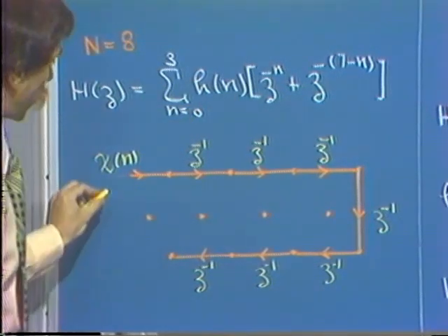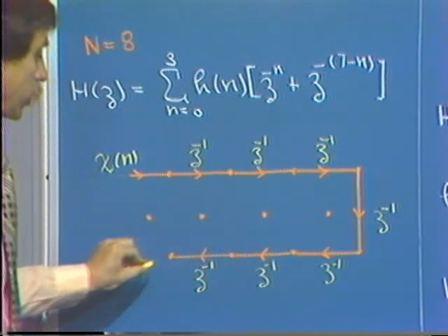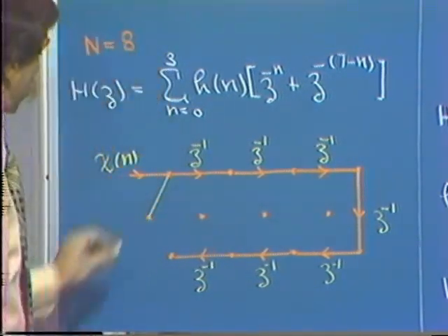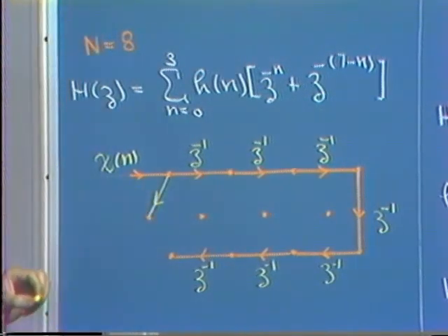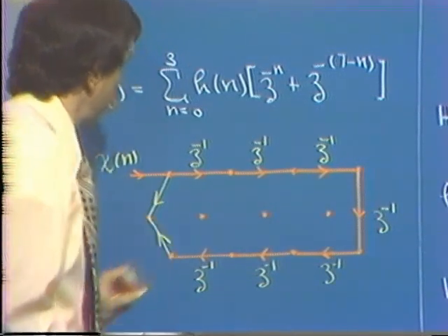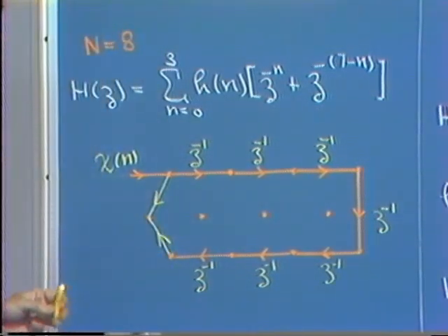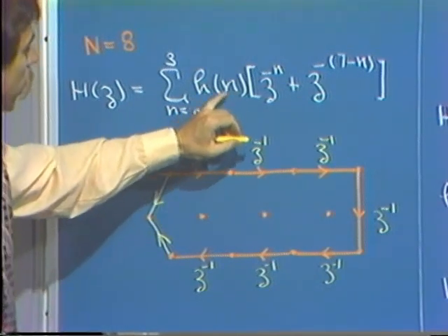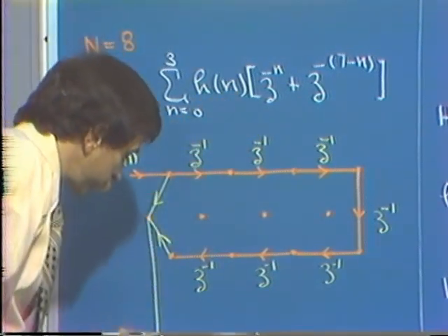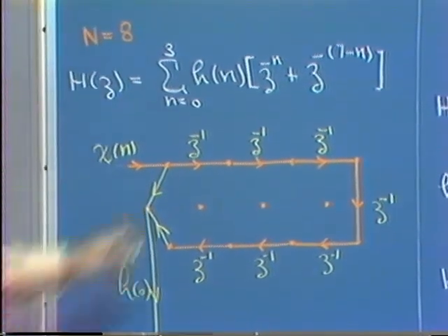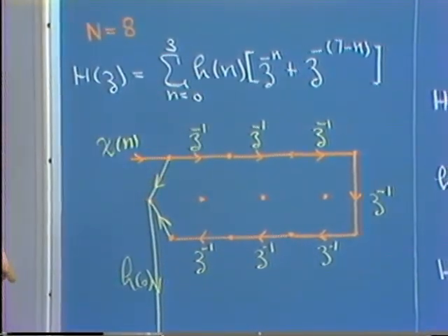And consequently, if we consider a chain of delays, as I've drawn here, we have the output before we go through any delays, added to the output from the 7th delay. That's looking at this expression for n equals 0. And the result of that summation multiplied by h of 0 to form the first term in this sum.